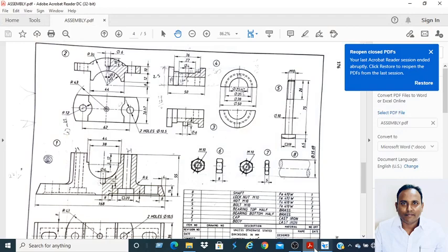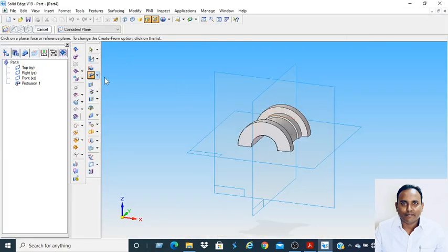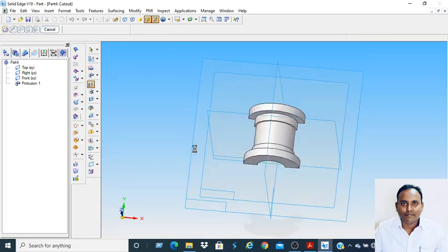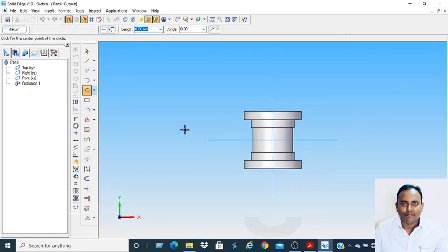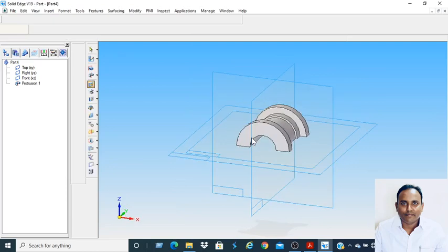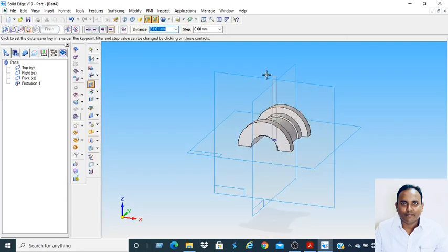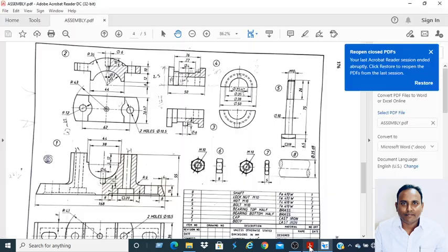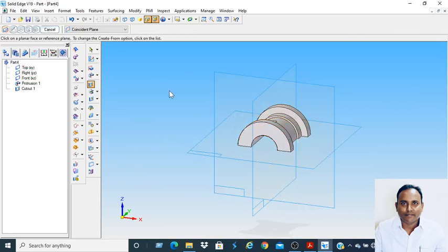Now the bearing top off is ready, and there is a hole of diameter 4. There is a hole of diameter 4 cut out. Select this particular plane, diameter, return, finish. Okay, now we'll assign the material for this one. This is bearing top of brass. Save.